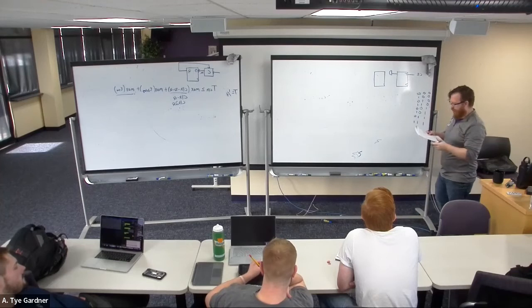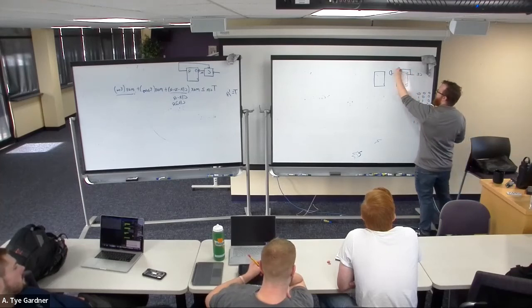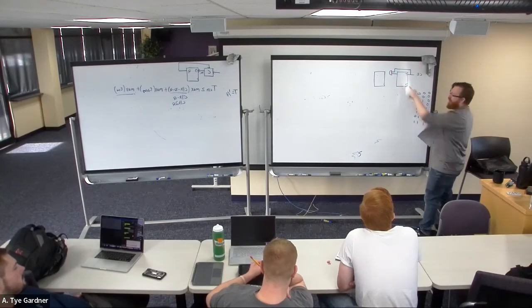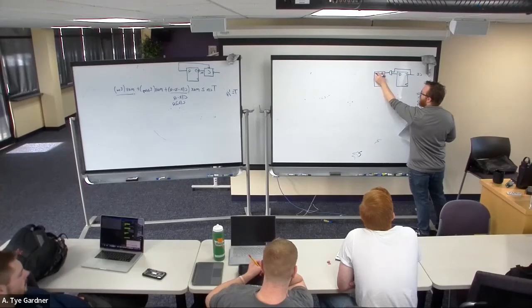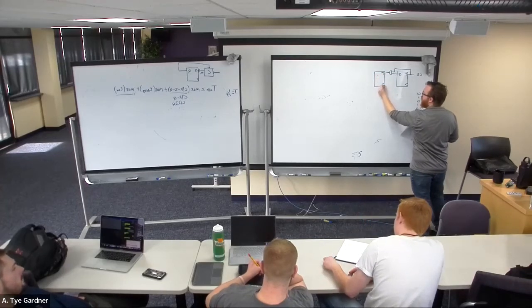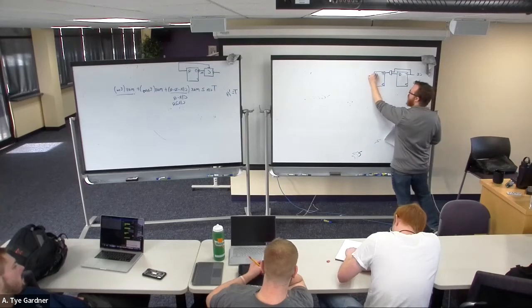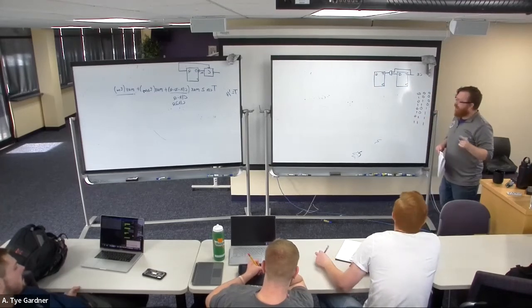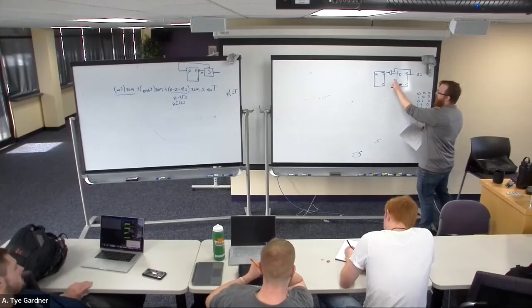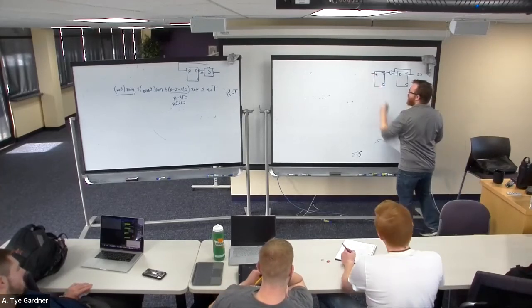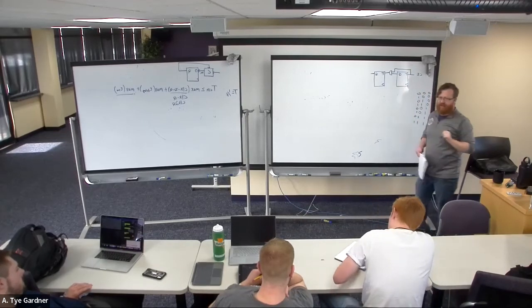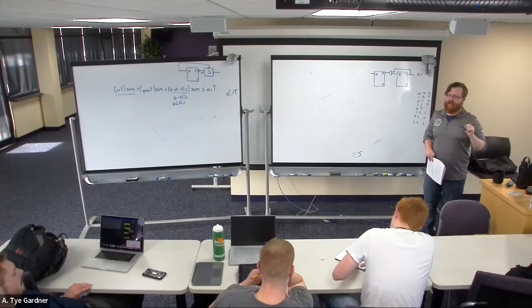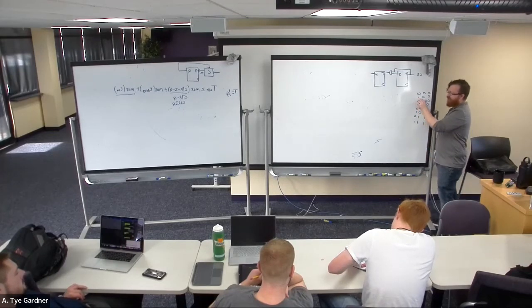If both of these things are true, which is to say, I want my clock to be enabled and this Q is a 1, then the only time that this T flip-flop updates its Q is if my clock is enabled and this is a 1, and there's a rising edge of a clock. So if there's a rising edge of a clock and this is 1, we can toggle this column. I now have a 2-bit counter.